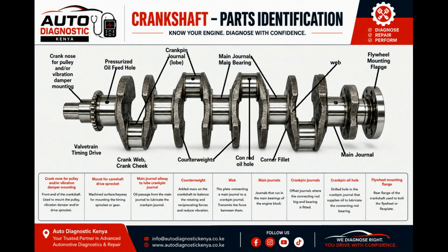A helical groove is machined into the crankshaft surface. Think of this like a coarse screw thread. As the crankshaft rotates, the groove helps move the oil back towards the inside of the engine. So instead of allowing oil to escape, the design helps return it into the crankcase, and some engines use more than one of those oil control methods.